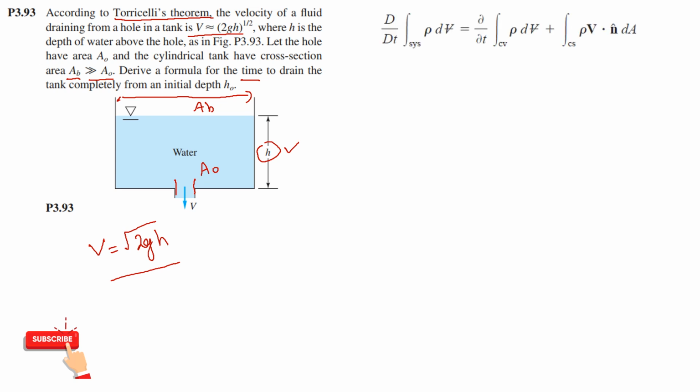So first let's look at our Reynolds transport theorem. This is how it looks when we put our extensive property B equal to m. In mass conservation, the total change in the mass is equated to 0, as you can recall from your mass conservation problems.